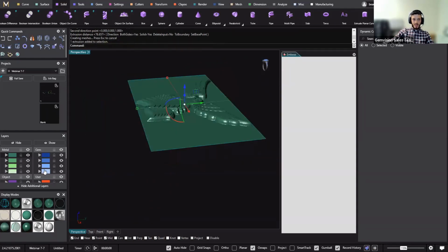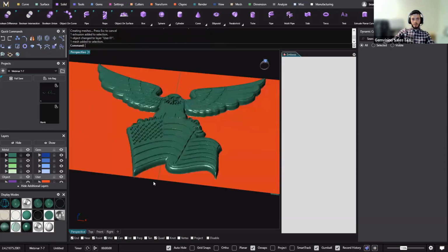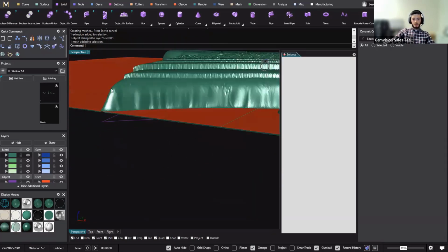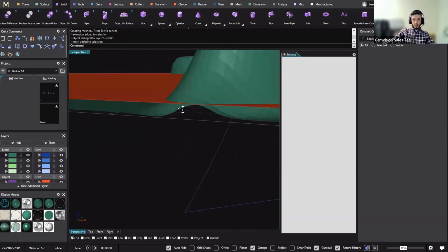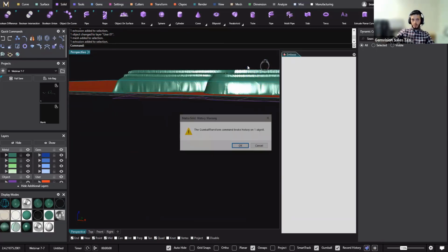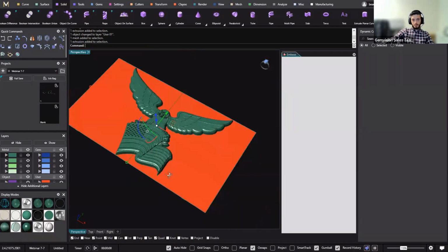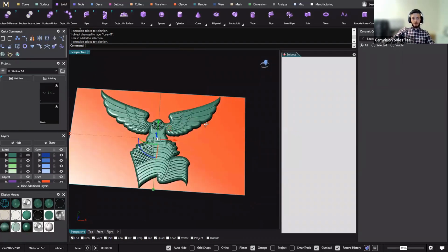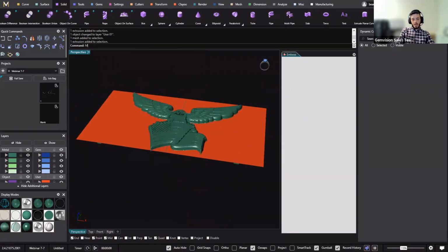So I now have a surface that we can color red and our object, which will be the green. Want to make sure there's no openings. Let's go up like 0.01. There we go. All right, so from here, we can do what's called a mesh Boolean. I can type mesh Boolean split.